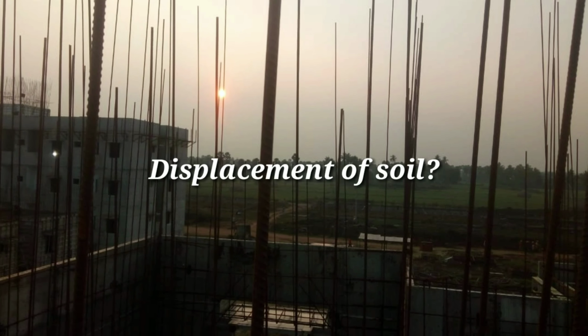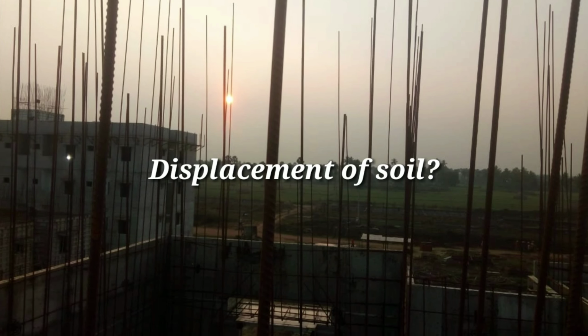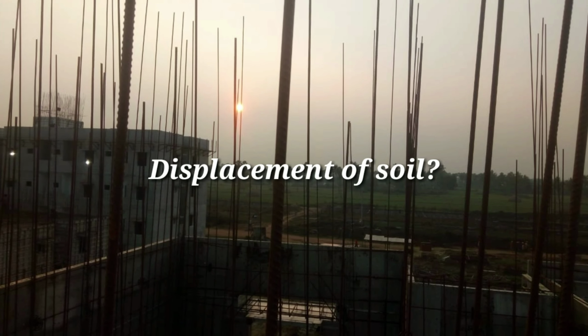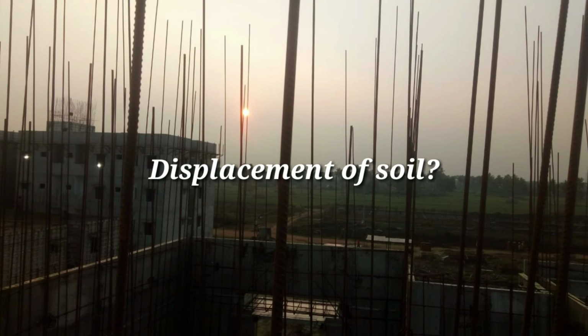And the last classification is displacement of soil. Based on the volume of soil displaced during the installation, piles are classified into two categories. Those are displacement piles and non-displacement piles.